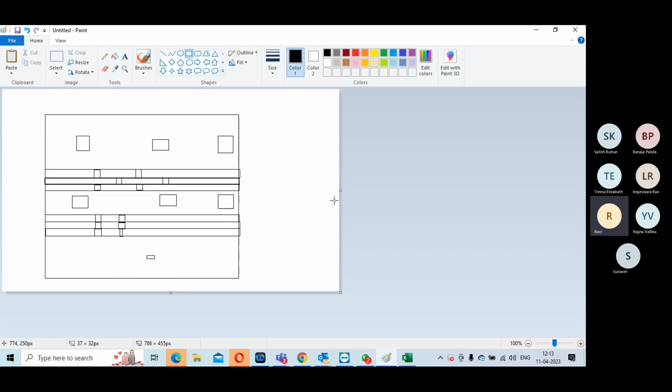So when do you first say your floor plan is good? It is when you look at your color code, your modules, and find that the modules are sitting in the manner your data flow diagram expects, and they are not getting split. Because once they are split, then again post ETS it could be a problem. So you have to ensure these things.